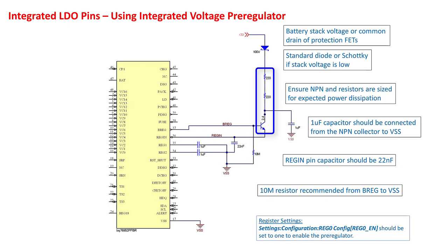and Reg2 outputs. For example, if the stack voltage for 16 fully charged cells is 68 volts, the voltage across the BJT could be 62.5 volts. If Reg 1 and Reg 2 are both driving the maximum current of 45 milliamps, this results in about 5.6 watts of power dissipated through the BJT. The resistors help to distribute the heat among multiple components rather than all just through the BJT.